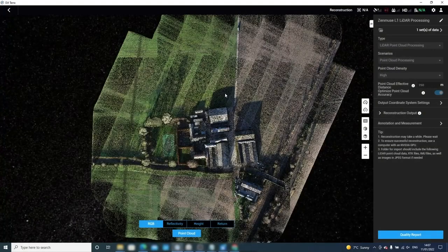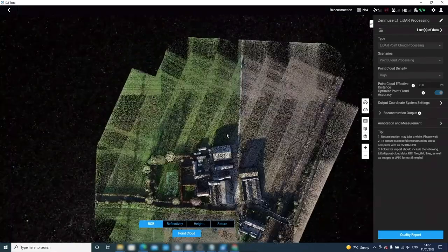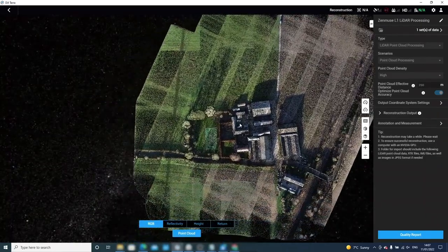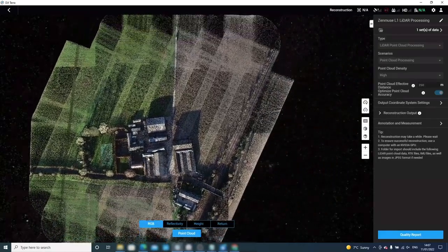There are a variety of tools included in DJI Terra that can be used to pan and take measurements from the point cloud. Firstly, we will introduce the pan tools included with DJI Terra. Using the left click of the mouse, we can pan around the point cloud and zoom into areas of interest from a top-down nadir view.